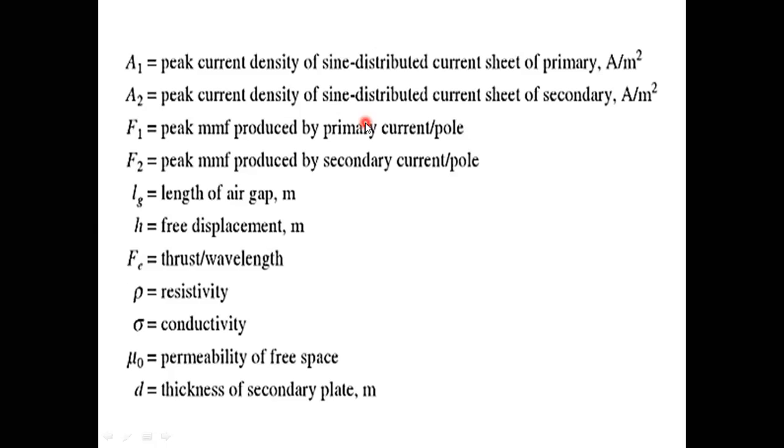The rotating magnetic field revolves in the air gap of a normal conventional induction motor. But a sinusoidal distribution is not possible in a linear type induction motor; we cannot get a sinusoidal distribution of the winding.